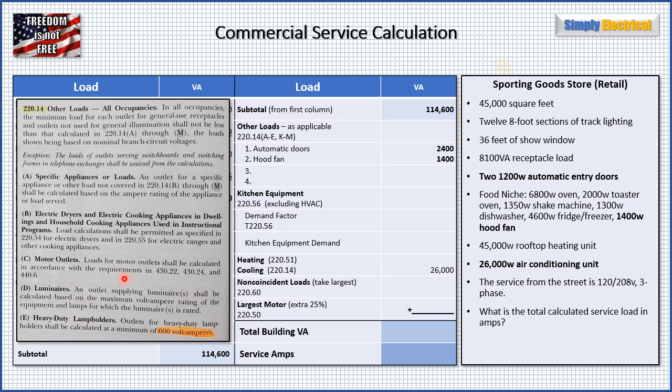Now we're going to be applying them to feeder and service calcs, of course, but only because we have a requirement of adding up our branch circuits to get our feeder value, right? So 22 technically doesn't apply to us working on feeders, but 24 does, and 440.6 does. We'll talk more about that later when we get to the actual motor calculation.